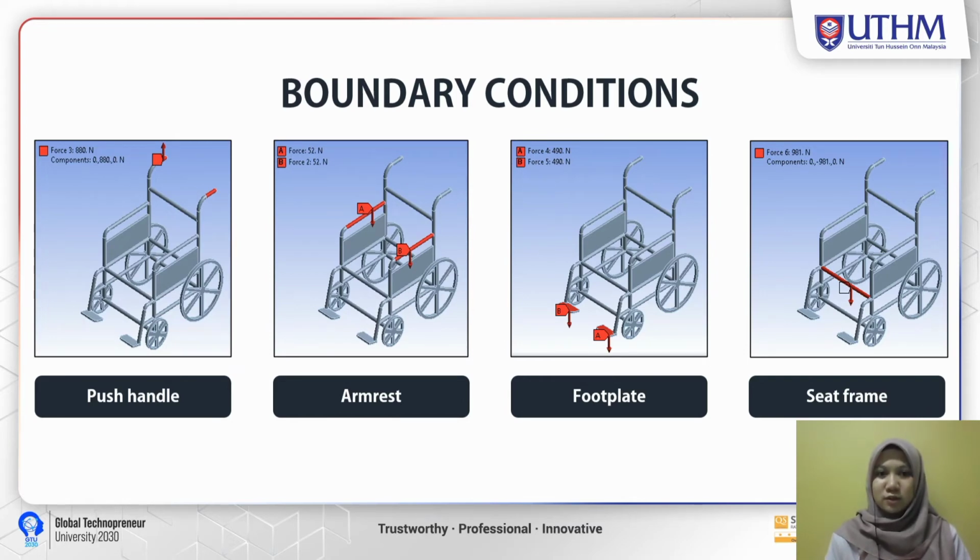After the boundary conditions have been set and the pre-processing steps have been completed, the model is ready to begin the solution phase. The solutions are defined in Mechanical according to the results of interest, which in this case are total deformation and equivalent stress.